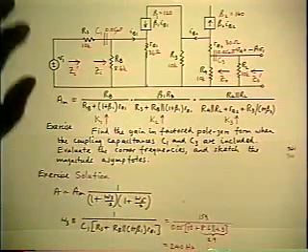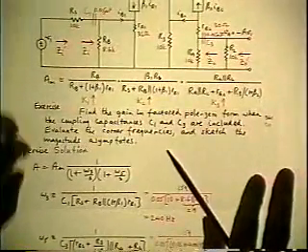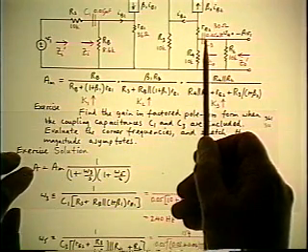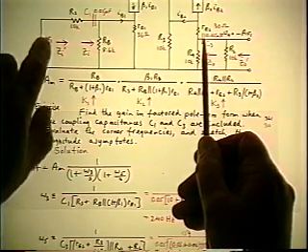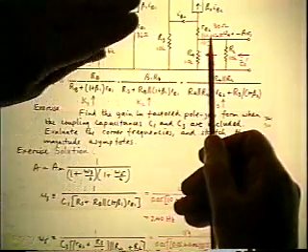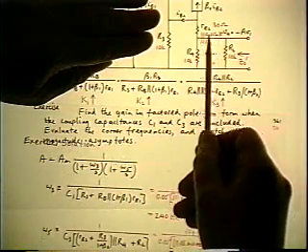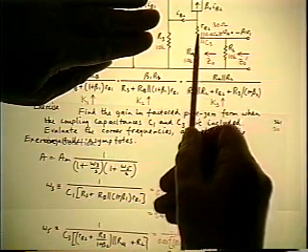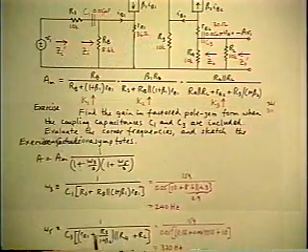To follow it through in detail, it's exactly the same sequence of steps. Replace the C3 with an independent source. Find the driving point resistance RD if the V1 is 0. If the V1 is 0, this generator is 0. So nothing happens to the left of the R3. So when you look in, you're going to see RL to the right, plus to the left, R4 parallel RE2 plus the reflected R3, which is this expression at the bottom.